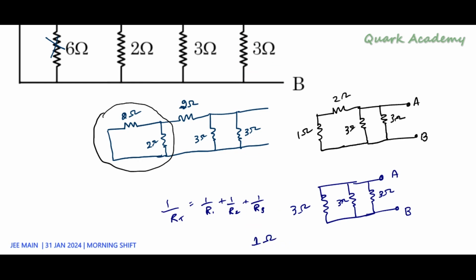And the other way is, if the same resistors are in parallel, then their effective resistance is going to become half in case two are there. Or if n number of resistors are there in parallel and all are the same, then the total resistance is going to become R by N. So here, since three resistors are there and each is of resistance 3, it is going to become 3 by 3, which is 1 ohm.